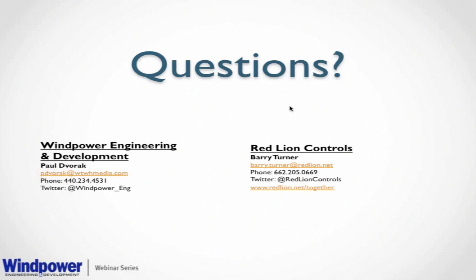Okay, very good. Peter asked this question. Are you using multi-mode fiber with ST, SC, or LC connectors? Yes. Yeah, we see people use multi-mode on all those different connectors, for sure. The main thing is if you have a short connection, then multi-mode is going to be what you want to use. Because multi-mode uses an LED instead of a laser, we want to use that for shorter runs. We want to use a laser type connector or a single mode module when we have a longer distance, so above 2 kilometers.